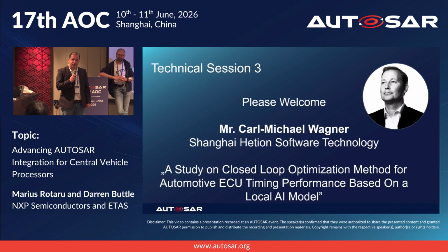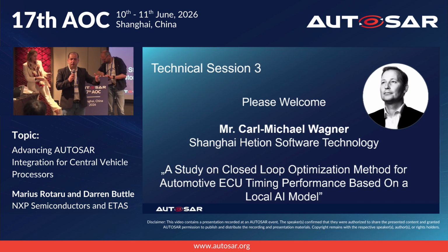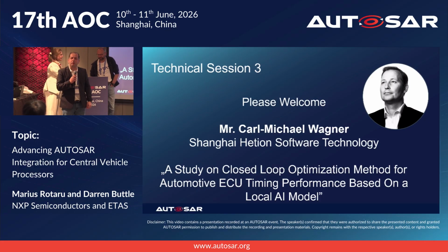Yes. And also for the external memory, do you have a single memory controller or kind of multiplex memory controller? Memory controllers. 2 memory controllers. The configurable quality of services per core, per cohort. So when 2 cohorts or 2 cores want to access external memory, at least two cohorts can do fully parallel access to the memory, but more than that, then you're kind of limited. There are limitations, but the quality of services. So, for example, if you have high performance, you configure the memory controller to ensure the right quality of services. Good. Thank you.